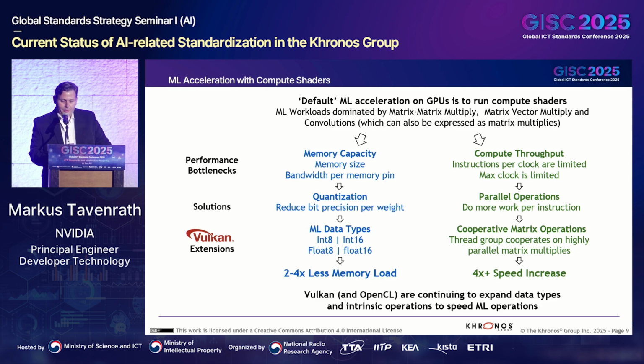For memory capacity, there's only so much memory we can attach to a chip, because of the maximum chip size you can buy, and then the number of pins your GPU can connect to the chips. But there's also a limitation on the amount of memory bandwidth you can achieve for each pin. And if you have a matrix-vector multiply limited model, most likely memory bandwidth will be a bottleneck.